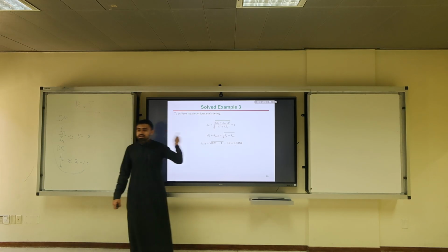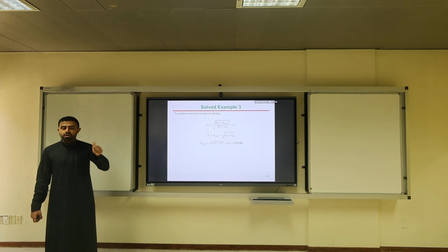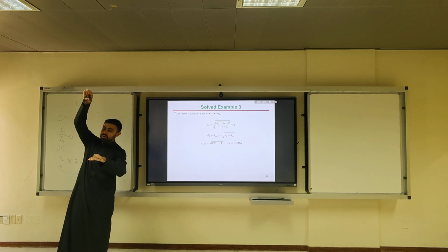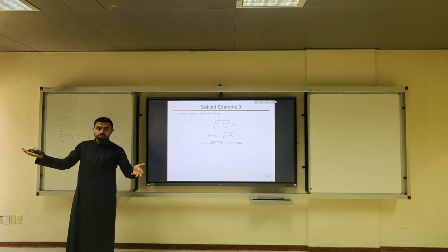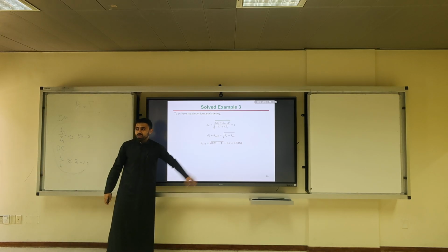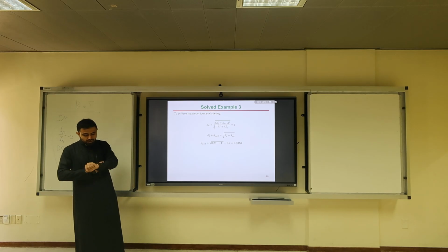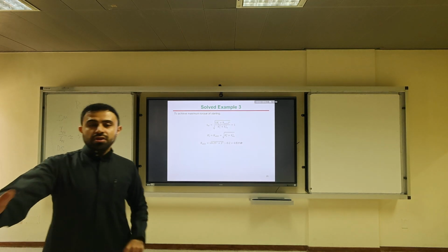So now, can I change the class of the machine by adding an external resistance? Yes. External resistance is the first way to control the machine by changing the starting torque from low to high. So if you have an elevator and you have a class B machine, what should you do? Add external resistance. With that, we finished the first set of slides, the introduction to induction machine. If you have any questions, do you have any question?